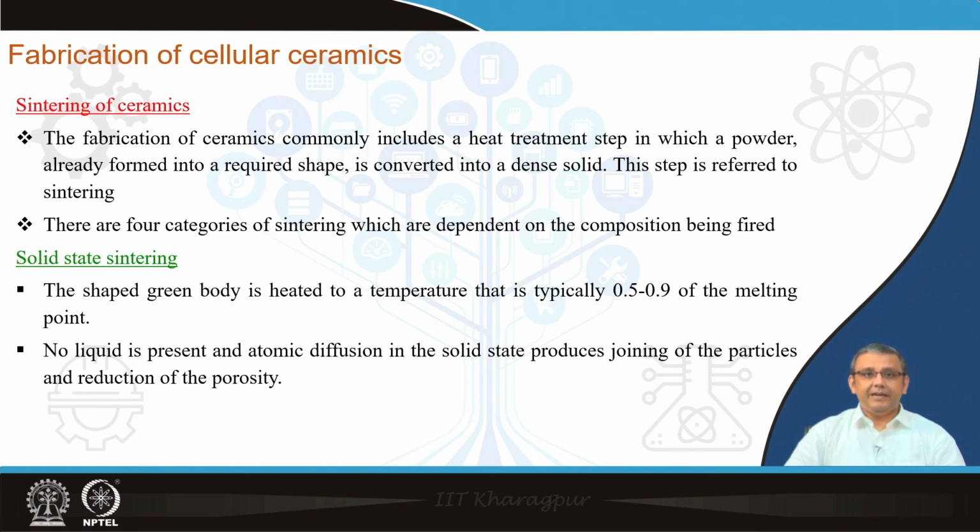So, sintering is typically employed to increase the bonding between the particles and also to impart strength to the porous body. Now, in bulk sintering, the aim is to attain almost theoretical density, that means even more than 99%, almost 100%. And in case of porous ceramic fabrication, although the aim is to have a significant amount of porosity, as I already mentioned, this porosity is provided by the pore formers.